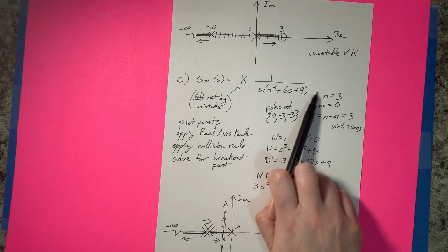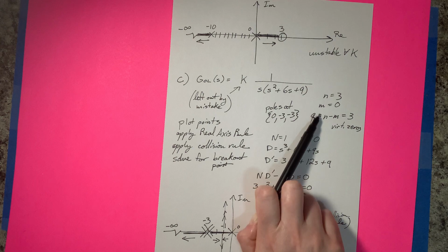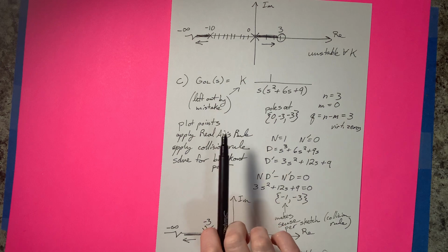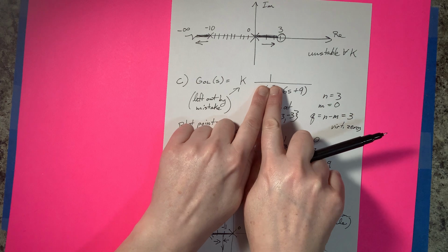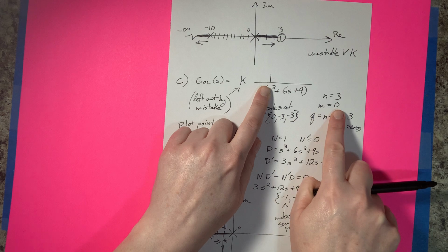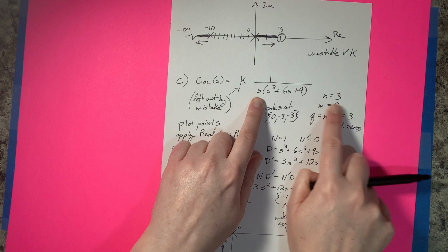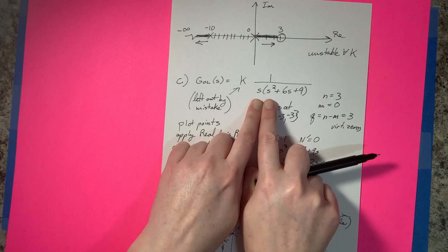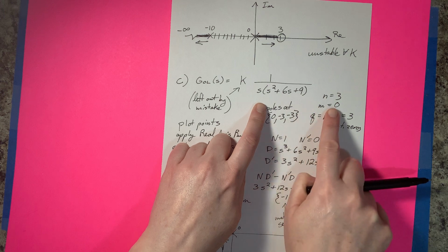But if you're evaluating the transfer function portion of this, you will look for the numbers N, M, and Q, and then find what the poles are. Or if we had zeros, we would find out what those zeros were as well. So here, looking at the numerator, we actually have no zeros, and so M is equal to 0. So we have no S's up here. N is the order, the number of poles we have in our denominator. We have a third order polynomial down here, so N is 3.